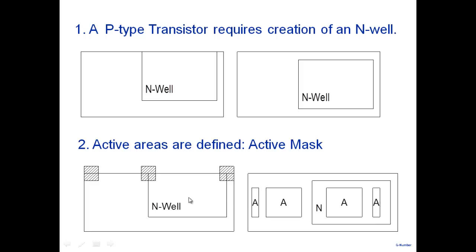So in this region, you have the normal silicon wafer that is there, P-type, or in this case N-type, because this is inside the N-well. All right, anything outside is all silicon dioxide. Anything outside active area is all silicon dioxide. The surface is not exposed anymore. In this region is where it is exposed.